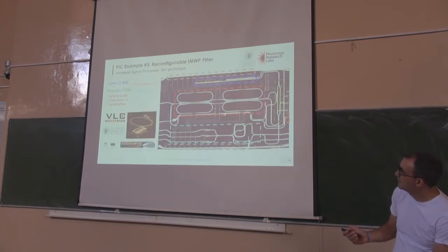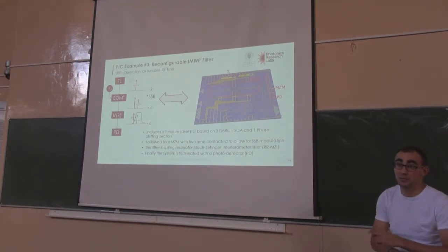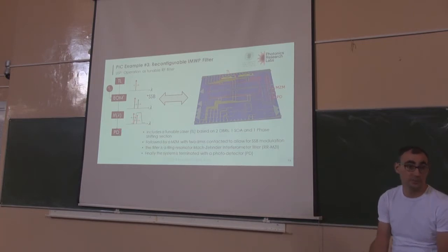Okay, auxiliary ports. So this works in coherent mode. Yesterday we discussed how to do microwave photonic filters, coherent regime and incoherent regime. Okay, this works in coherent regime. Actually, you have a laser, you modulate in a single sideband fashion in such a way that you only have a single sideband. This is your optical filter, and depending where you put your optical carrier and the distance of the subcarrier in the RF domain, when you beat them together, you will see one or other type of filter.